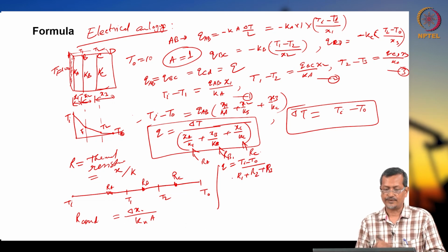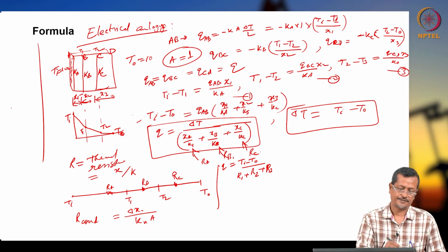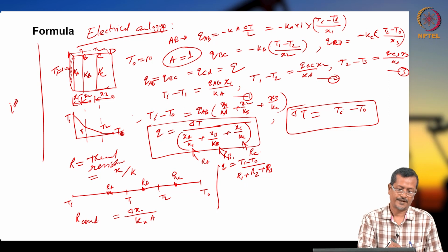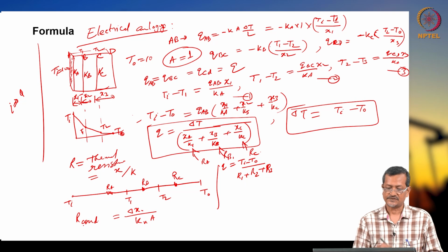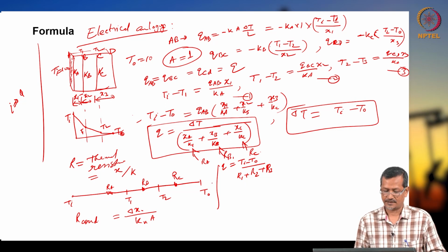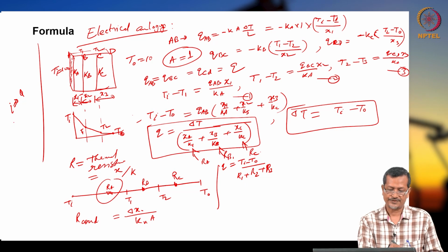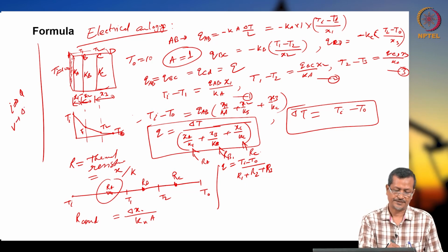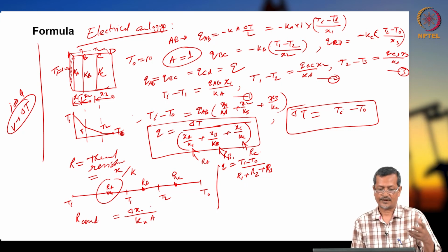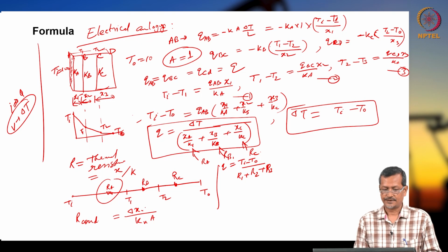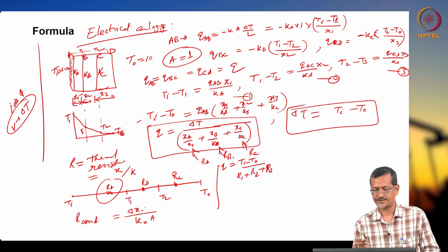Okay. So whenever you are creating an electrical analogy, I will be implying Q as heat transfer rate. Okay. Resistance you have already seen here, R resistance we are showing, and voltage is temperature difference. Voltage will be del T actually, temperature difference. So if temperature difference is high, more current will be passing. Okay. So this way you compare an electrical system with a thermal heat transfer system.